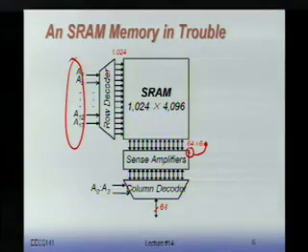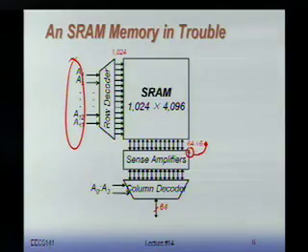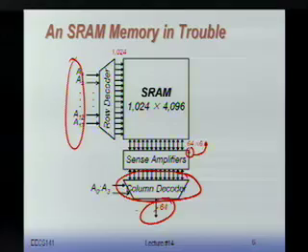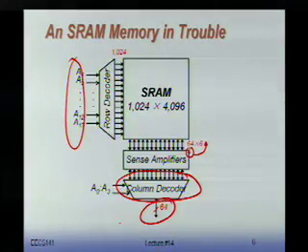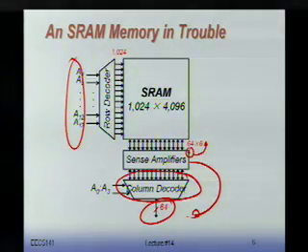Now when you read all those 4,000 bits out, the column decoder is going to pick the right 64 out of that. So we have a column decoder that basically takes 4,000 bits and creates 64 bits at the output. Actually, this drawing puts the sense amplifiers before the column decoder. In the real implementation for an SRAM, you're going to put them behind it. The online project description is right. Yes, this is the old drawing.